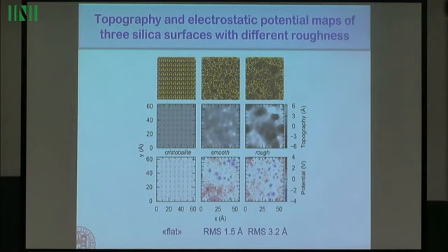The bumps in the surface are of the order 1.5 angstrom, and this 3 angstrom. You could say this is a theoretician's roughness. This is too small for reality, but not true. You can buy glass, the one that is used to support magnetic particles in hard disks, for example, with this root mean square roughness.